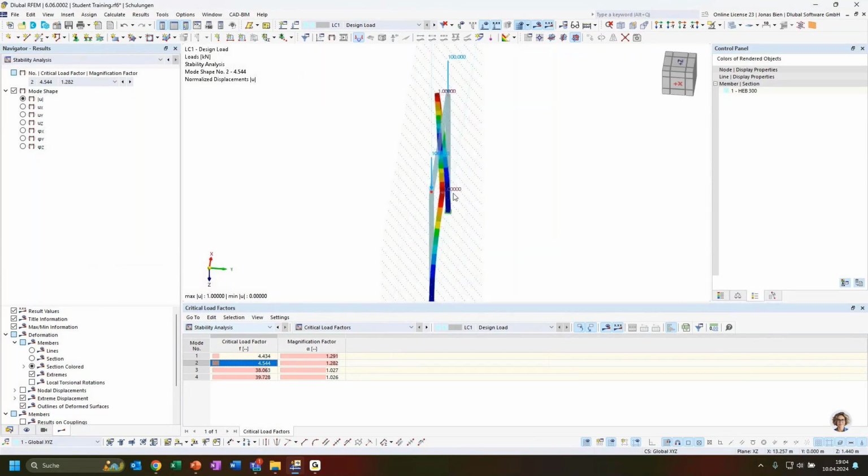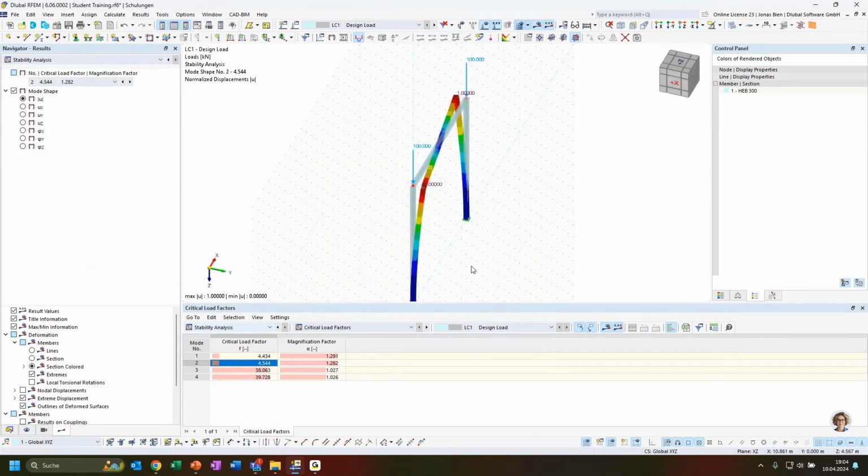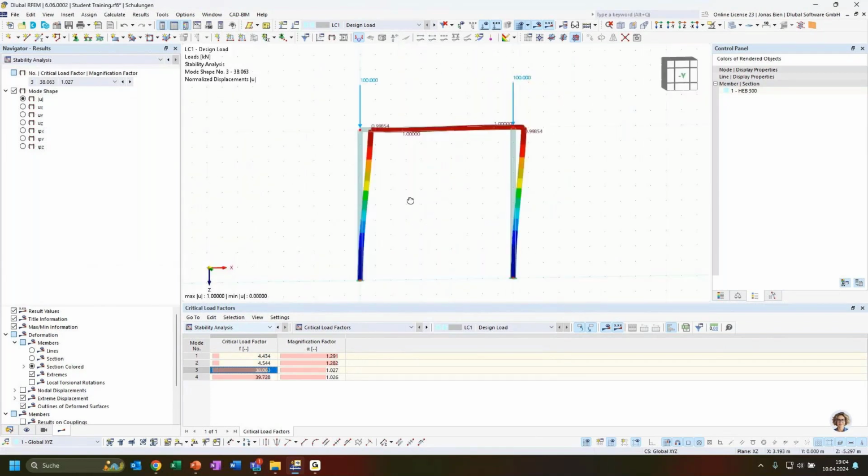Okay, this would be asymmetric buckling, but also out of plane, so around the weak axis of each particular column. In this case, the girder would also not do much. But now, when we analyze the third mode shape, that represents in-plane buckling of the frame that we just generated. For this kind of buckling, the critical load factor increased from 12 to 38, because we have built a frame, and this girder, this horizontal member on top, actually increases the stability of the system significantly.